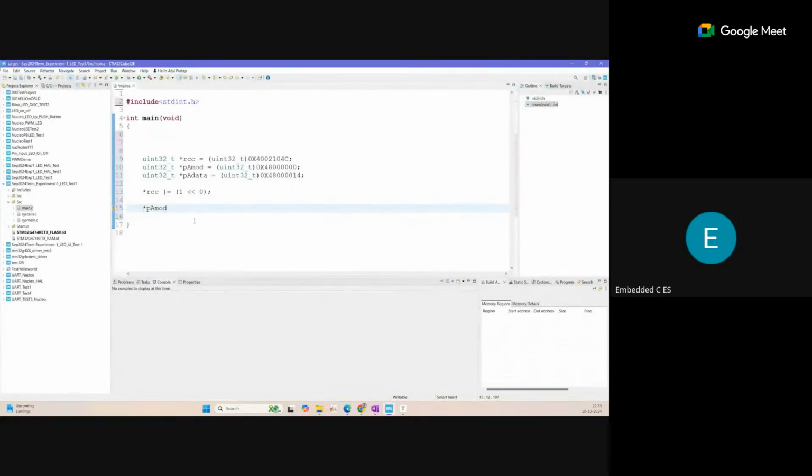By the bitwise operators. First, we will reset the bit to 0, so an AND operation is required. But with which value? That is a 1, shifted how many times? 11 times, correct? Yes, 11 times, and after that we invert it. Because we want to set the 11th bit as a 0, that is done by this.